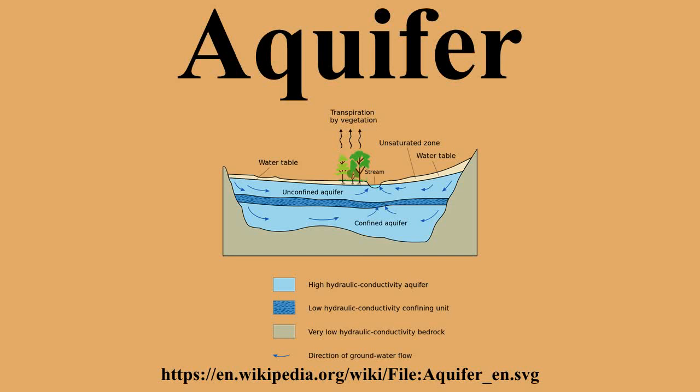This can saturate a small zone above the phreatic surface at less than atmospheric pressure. This is termed tension saturation and is not the same as saturation on a water content basis. Water content in a capillary fringe decreases with increasing distance from the phreatic surface. The capillary head depends on soil pore size. In sandy soils with larger pores, the head will be less than in clay soils with very small pores.